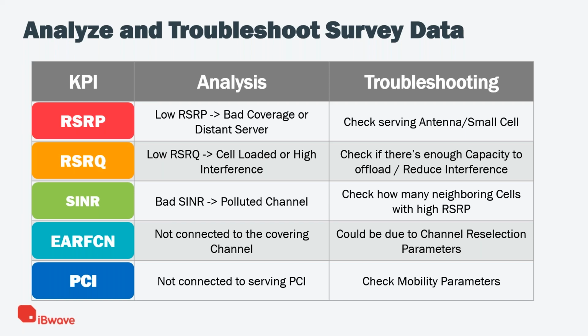In the most common use case scenario, it could be just a PIM generated, especially if you're doing DAS. It could be a product of intermodulation, just two frequencies mixed into the DAS, and then there's some bad connector somewhere generating interference in a third intermod, and then you see it in that particular channel, and it might make your signal bad. So that's some troubleshooting you need to do. Otherwise, it could be something external.